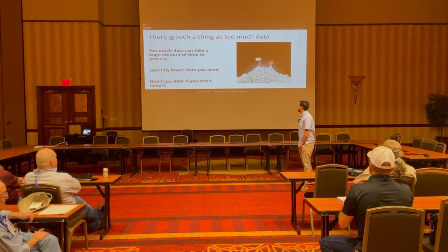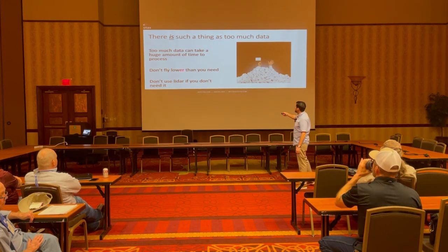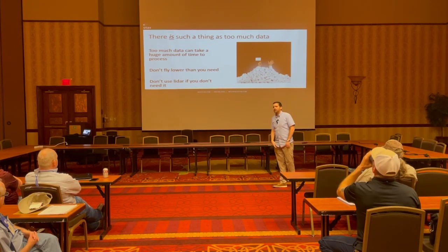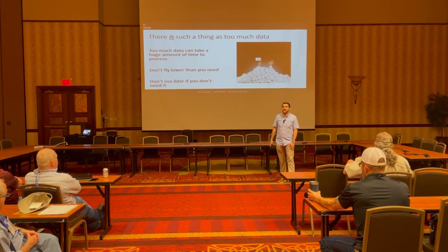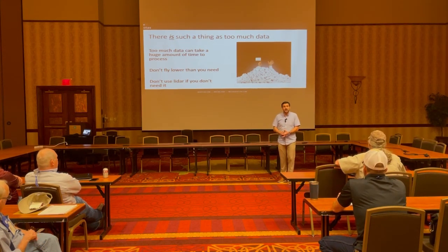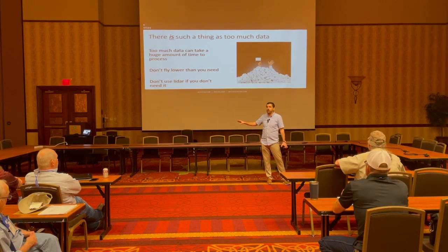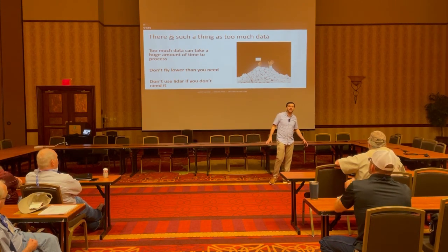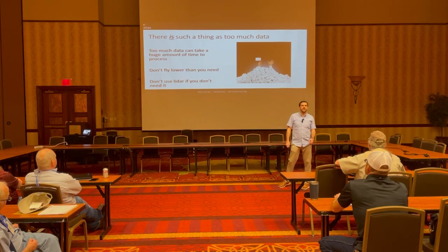We do. We care about the cost of the data. So don't fly lower than you need. Don't use LiDAR if you don't need it. You'll wind up drowning yourself in data, and it often winds up killing a drone program entirely, because you don't use the drone as much, since you know how much of a pain in the butt it is to process the data because you didn't get everything right in the beginning.